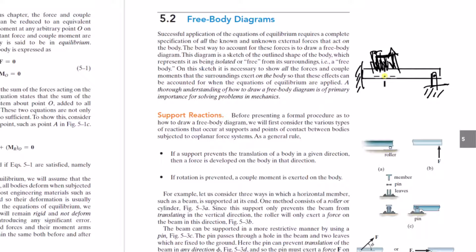So now after you, the Hulk, applied that, you're going to go away from the beam in empty space, moving in a linear direction, and also your body's going to be spinning. But again, the only thing you could possibly apply is a linear force or a couple moment. That's it. There are no moments about points when you're thinking about free body diagrams. It's either force or couple moment. Technically, it's only just force, right? Because even this couple moment is really just two forces. But we think about it as just forces and couple moments.